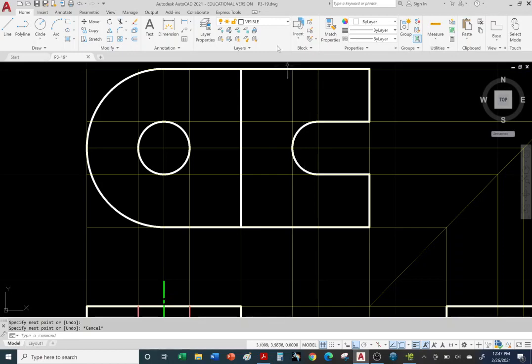All right, so let's throw in our green center lines. Okay, so center line. Okay, so extend beyond the circle. See, it's trying to snap. Okay, so let me turn off object snap. I'm going to show you some other ways later on.